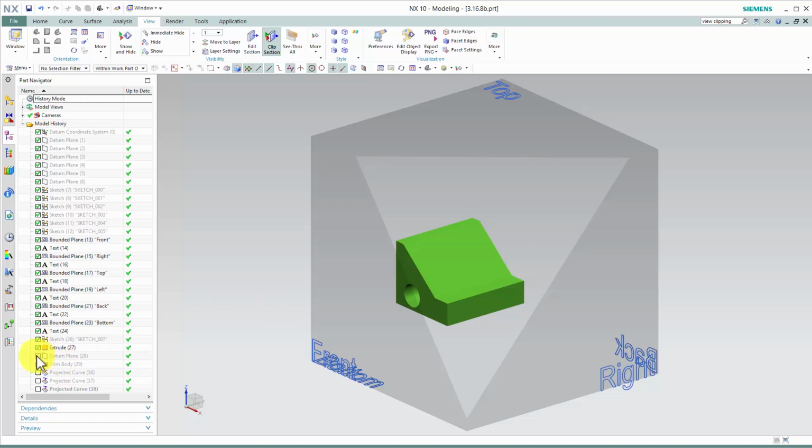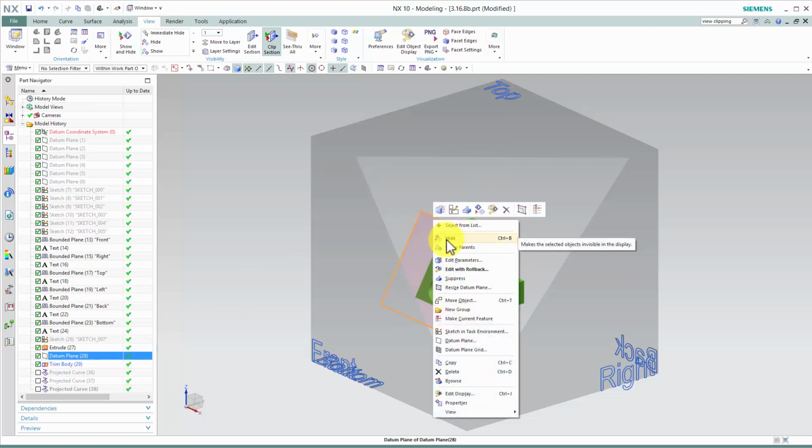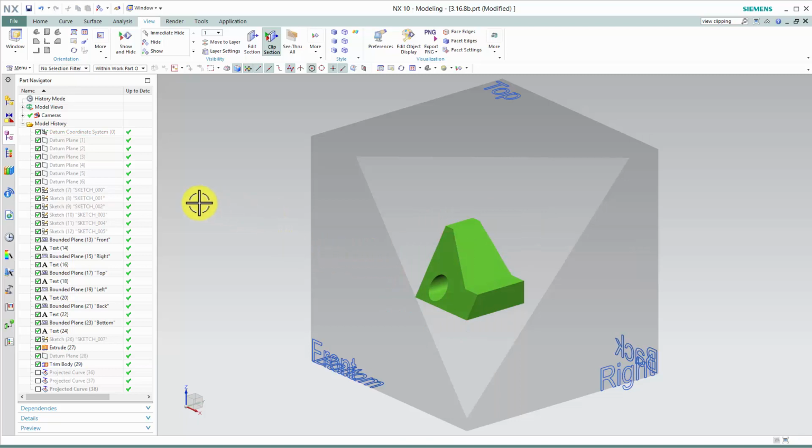But once again, what if we had defined a clipping plane and used that clipping plane to actually trim away part of this object? Now once again, we want to have you practice sketching what the front orthographic view would look like, what the right orthographic view would look like, and what the top orthographic view would look like.